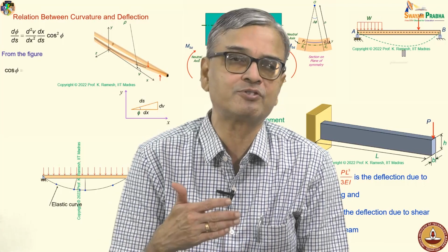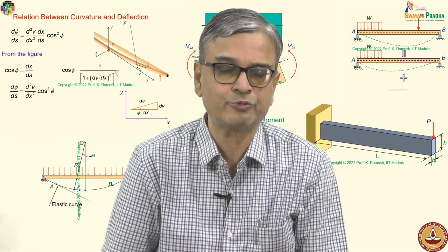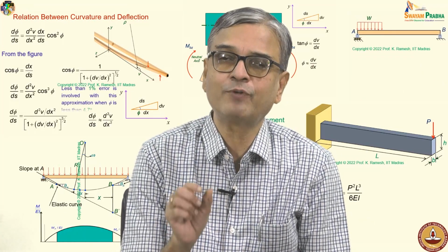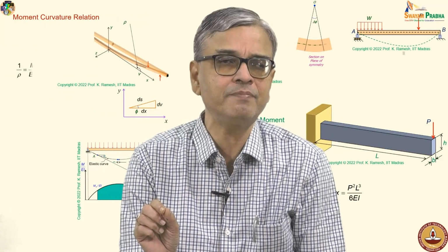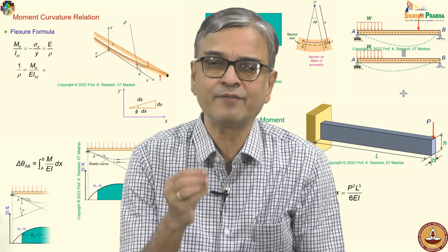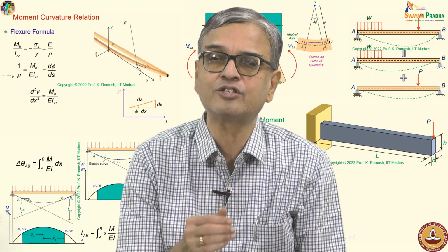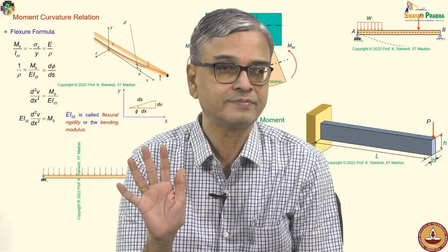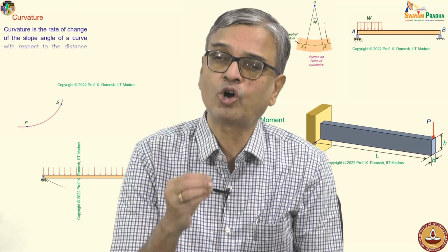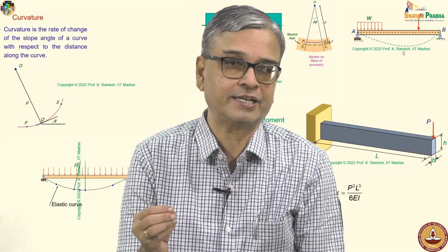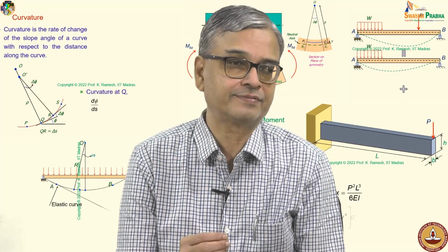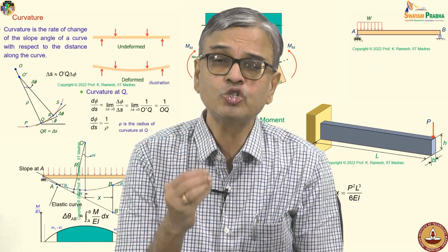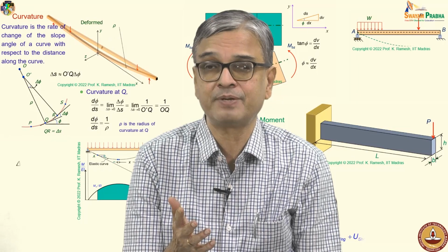People also have developed singularity integrals, which we are not going to look into, because it becomes a mathematical exercise. If you are able to write one single equation for the entire length of the beam, the equation is valid and we have followed a sign convention, you get the slope and deflection as per the sign convention without any difficulty. The same thing applies also for using the load deflection and then doing the integration. And I said the load deflection equation which I have given is also valid for statically indeterminate beams.